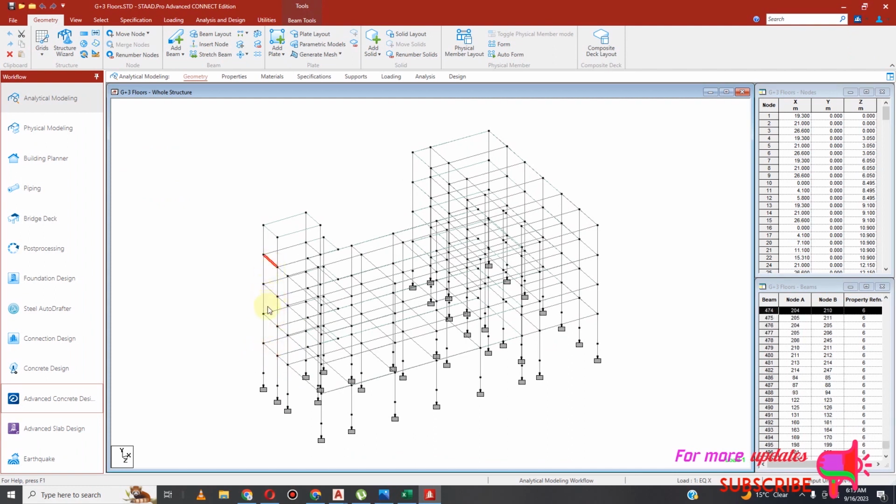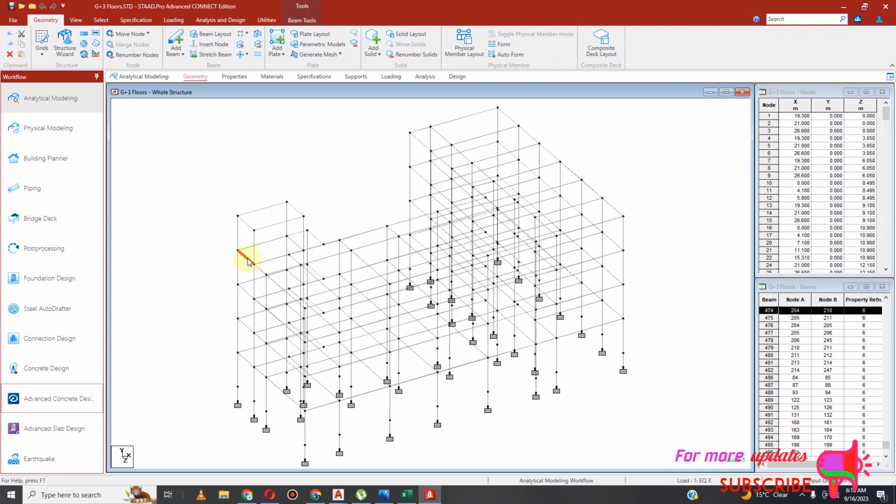And remember, we have a staircase. We did not include staircase load, and staircase load is normally about 22 kilonewtons, so we should include staircase load at this point because we did not model our staircase. But remember, we already used a bigger cross section of 400 by 200, so that one could save the day instead of just having to redo all that work. You know that your columns are safe.